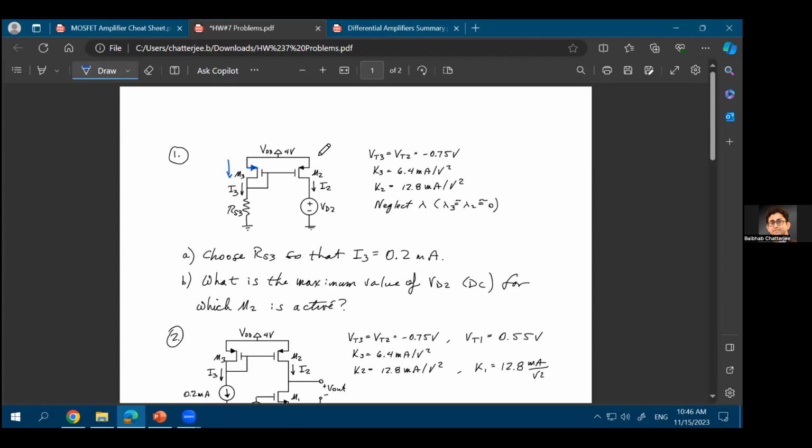Okay. So if that is true, the way you should analyze any kind of PMOS-based circuit is as follows. For your NMOS, you know that if your VGS is more than the threshold voltage, then the transistor is on, right? That's for your NMOS. For your PMOS, just take absolute values. The absolute value of VGS has to be greater than the absolute value of the threshold voltage. Then the PMOS transistor is on. If it is not the case, the PMOS transistor is off.